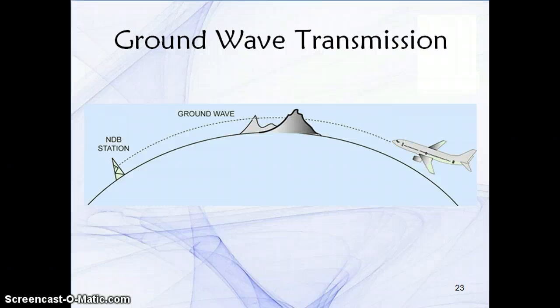Since radio propagation is somewhat unpredictable, such services as emergency locator transmitters, in-flight communications with transatlantic crossing aircraft, and some television broadcasting have been moved to satellite transmitters. A satellite link, though expensive, can offer highly predictable and stable line-of-sight coverage in a given area. The ground wave, these are the lower frequencies, mainly between 30 and 3,000 kilohertz.